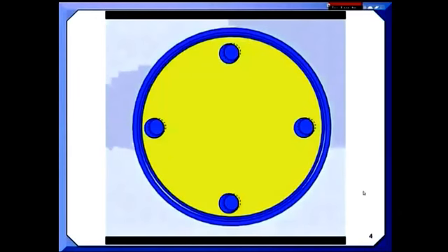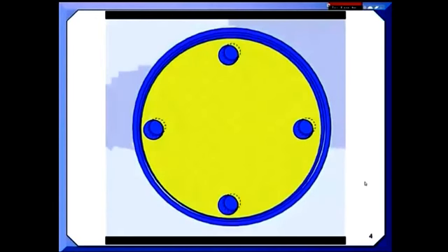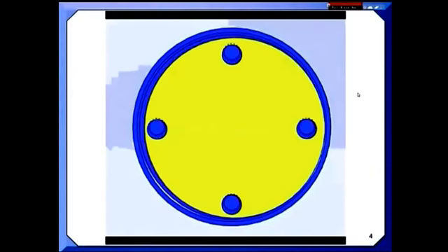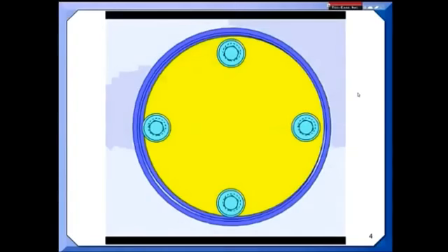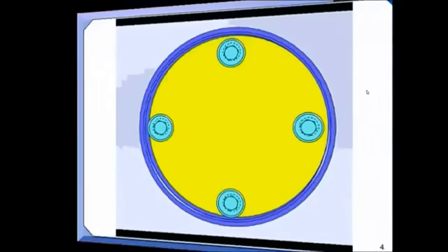This animation illustrates why we allow the M on the datum feature. I can shift it around as long as the pattern is maintained so that I can get all four screws into those clearance holes. And I hope this helps everyone appreciate why you cannot treat that M on the datum feature reference as a bonus. There is a shift that is allowed, but the pattern has to be maintained.